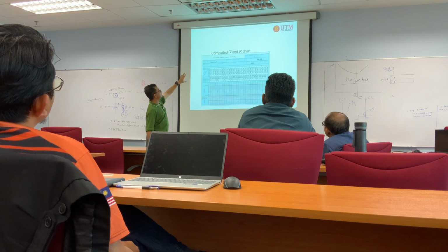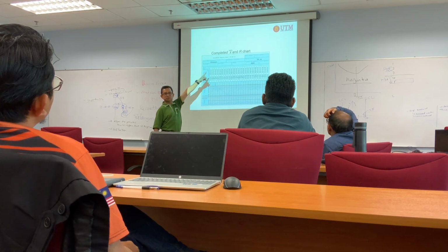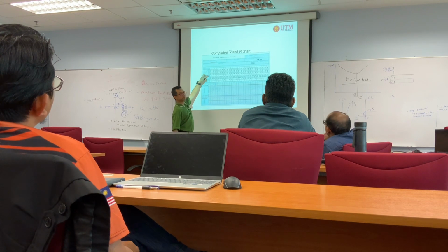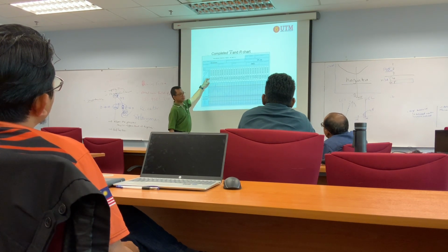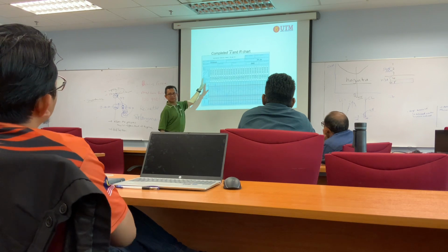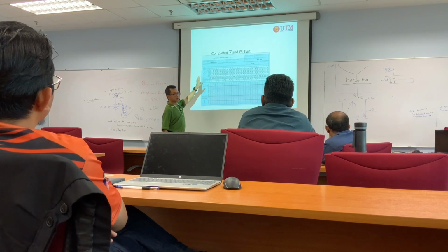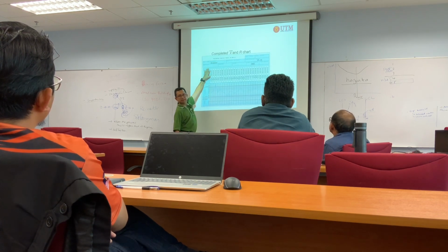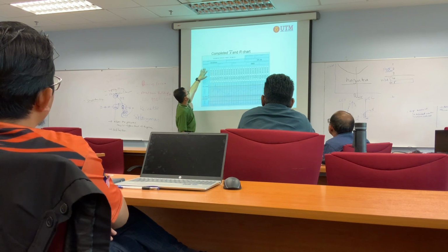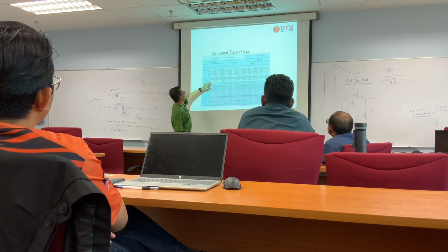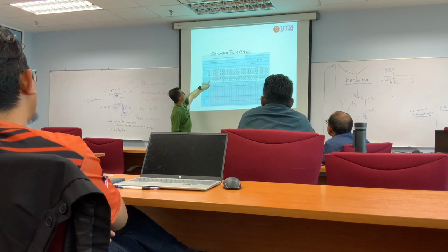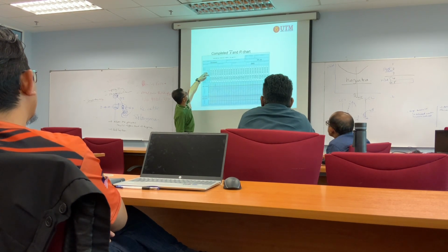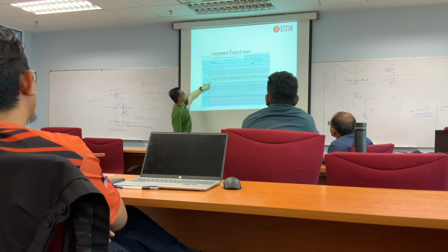Because this is X bar, the bar is average, the mean. So we have to get a couple of readings, 4 or 5, 6, whatever. Actually, it will affect the formulation also. Later I will show you. So let's say we read 4 times for this one. This is the sum, and then this is the average. 112 divided by 4, we got 28. So the range, the highest 33 minus the lowest 24, we got 9.